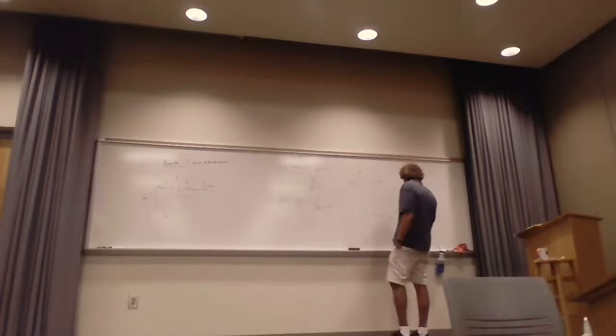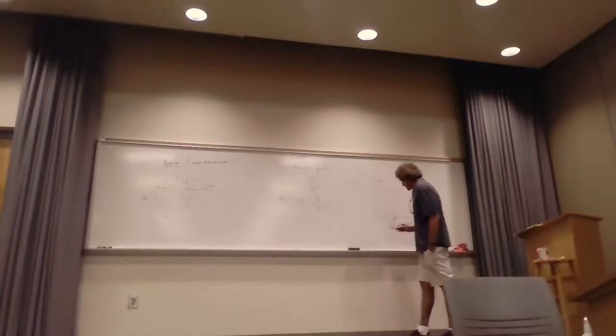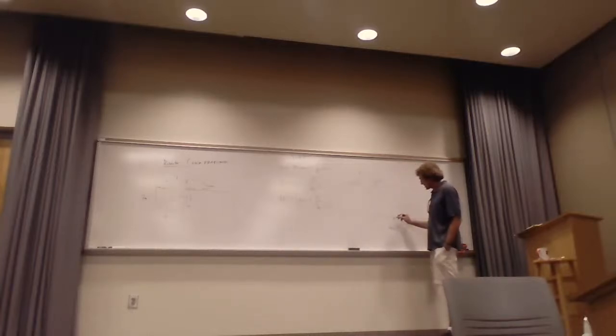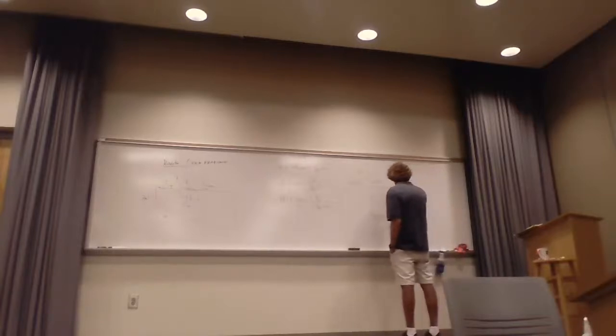The first cut frequency, the first point where it starts dipping, is going to be 1 over 2 pi RC. And mark this down, this is not what we're quoting. It will start coming down at a rate of 20 dB per decade.